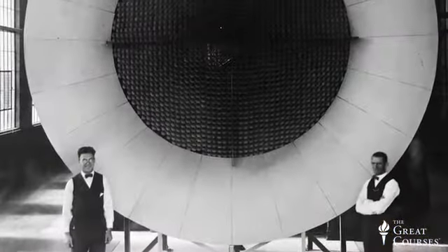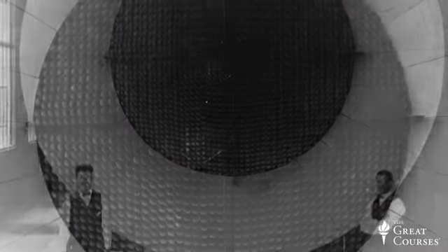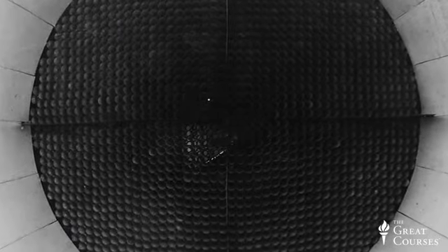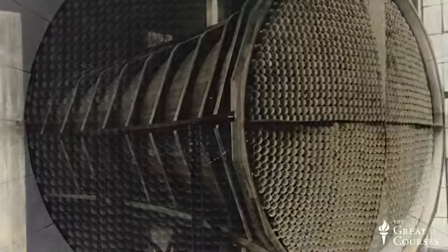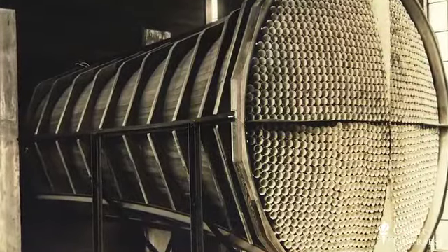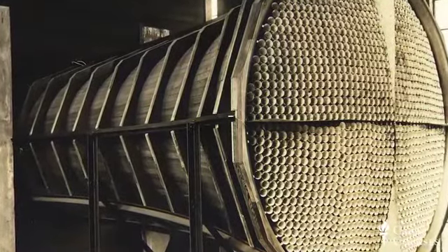It turns out that the chaotic motion of the paper airplane is due to the swirling flow from the fan. The way to counteract this is to use flow straightening elements to remove the swirl. Wind tunnel designers routinely use a honeycomb material for this purpose, which breaks the flow up into small segments and causes the transverse components of the velocity to dissipate.